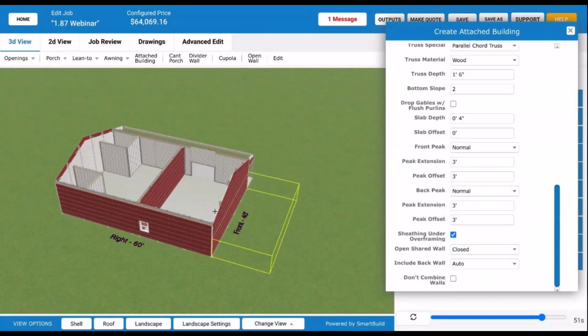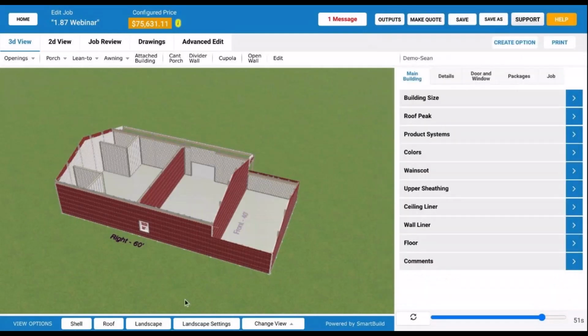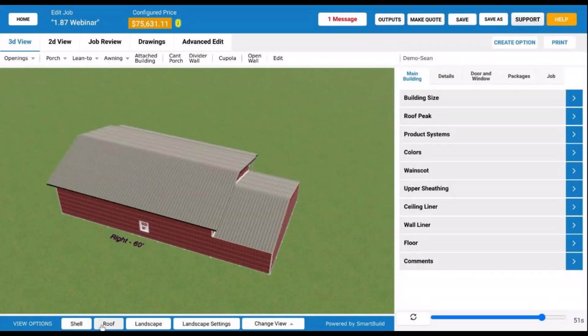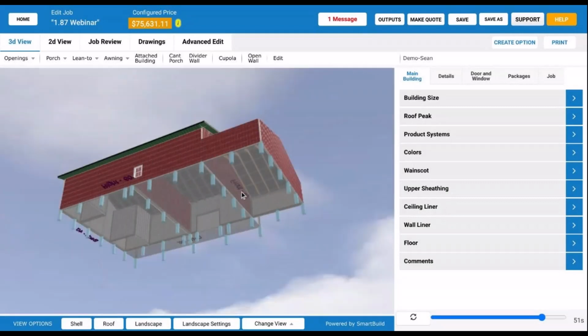Yeah, but if you click ceiling framing on, then you have to go in. If you only want ceiling framing on one building, you'll have to go in and click off ceiling for every other roof. So that gets pretty annoying, I do know. If it's just turning off the ceiling for just one, it's not such a big problem. But if you only want ceiling on one part, that gets pretty complicated on the bigger buildings. You can actually do just the opposite. Go in and advanced edit, select the only roof you want to add the ceiling and add it to that ceiling.